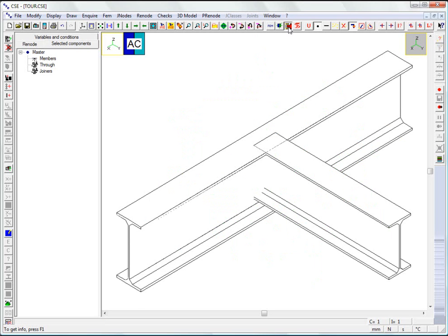Initially, only the members are present, and since the FEM model has no axial offset defined for the secondary beam, this overlaps the main one. The secondary beam does, though, have an offset that brings its upper edge to the same height as the main beam.